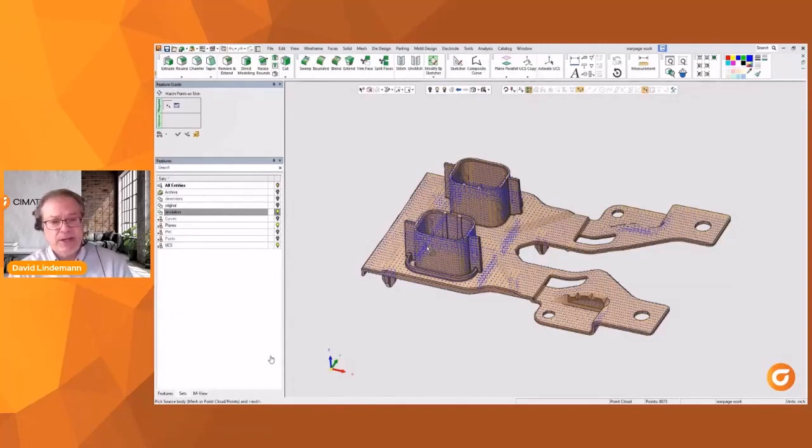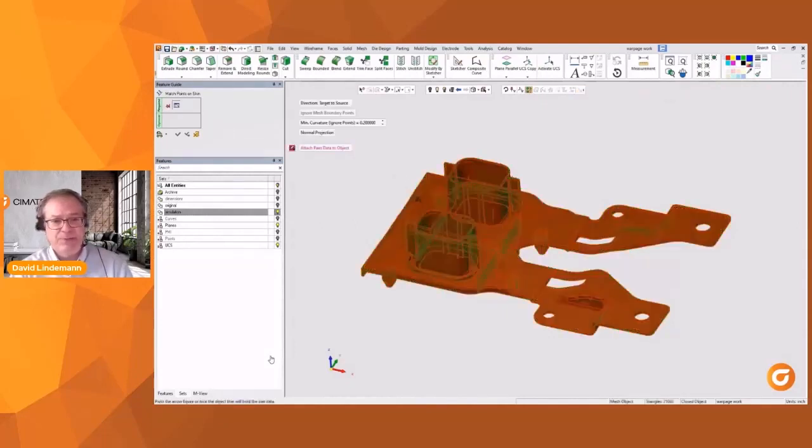All right, so let's take those points now, and we're going to work with the STL. We're basically going to snap them down to the STL surfaces and compare the distances. The way I like to do it is to keep a separate file. So this is a CSV file, or comma delineated kind of file. I do that because I may have other iterations of this. I may go back to the simulation, tweak the water, run it again.